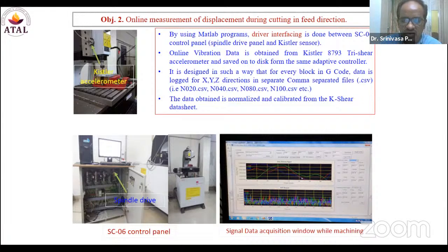And if these two are ignored, after quite some time, the cutting tool will fuse to the workpiece due to rubbing action. It's like a welding. When welding is formed, it will not allow the workpiece or cutting tool to rotate. It affects the inherent, inbuilt controls of the machine, not the controller, and the functionality of the servo motors. If the servo motor stops functioning, there is no need to go for any programming. So this much damage can happen if we ignore the output process variables.